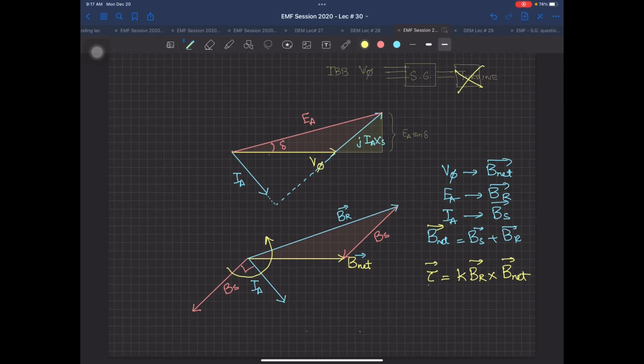We are moving the generator in the anti-clockwise direction. And it's a generator, but it has a motor phenomenon taking place inside it, which is trying to move it in the counterclockwise direction. So they are trying to cancel each other, but in steady state it's rotating because it's working as a generator. It's the same thing. If you remember your DC machines, I told you there is generator phenomenon happening inside a motor, and similarly there is motor phenomenon happening inside a generator. So it's the same thing happening over there.